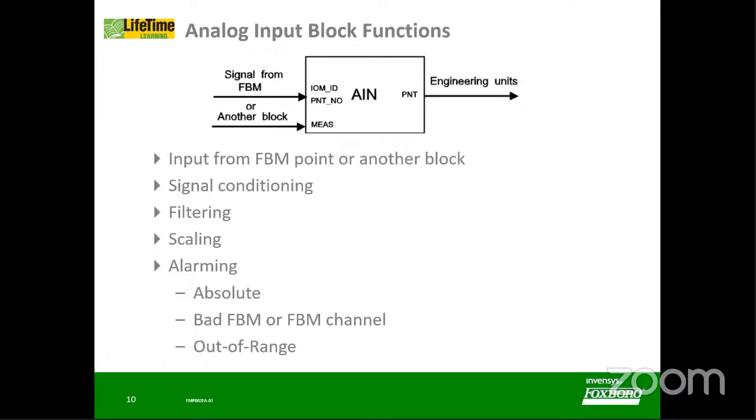This is one of the ways a DCS system works: even if you do not have a smart transmitter, by simply using analog transmitters you can have fault monitoring, or you can do fault analysis of the transmitter just sitting in the control room. This is one of the advantages of using the Foxboro DCS system.